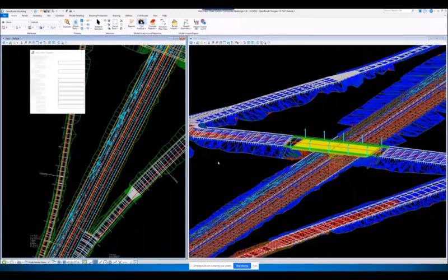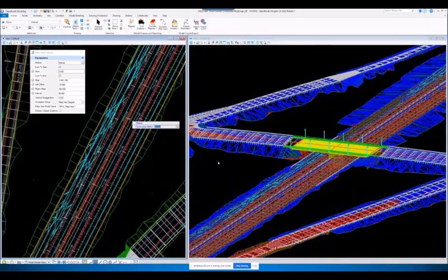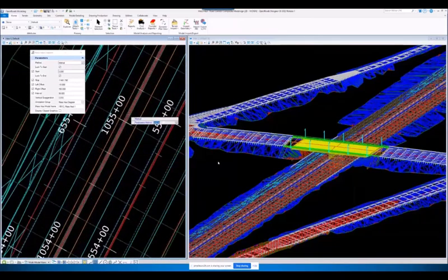So I'm going to kick this off here, and I'm just going to go to the mass haul diagram, appropriately the dump truck. And I've got a couple methods I could choose. I could do an interval, because I'm looking at this from a construction point of view. I don't have name boundaries. I don't really even care about name boundaries. I want to know which way to move dirt. I'm going to look at the alignment. In this case, it's going to be the center line of I-95. Once I pick that up, it's going to determine the limits of that.